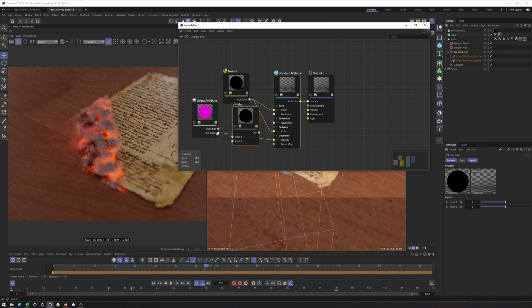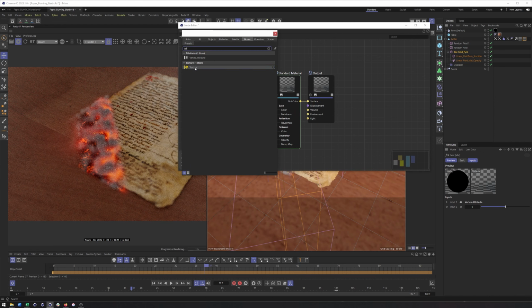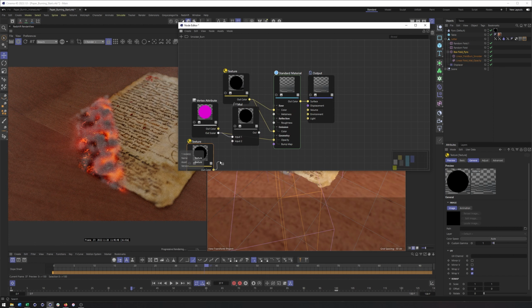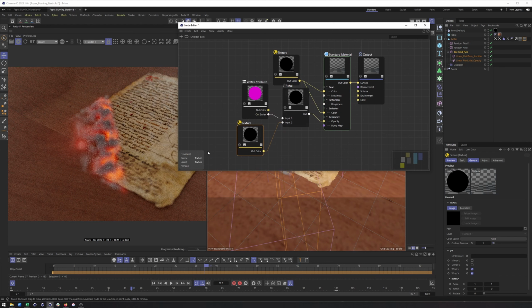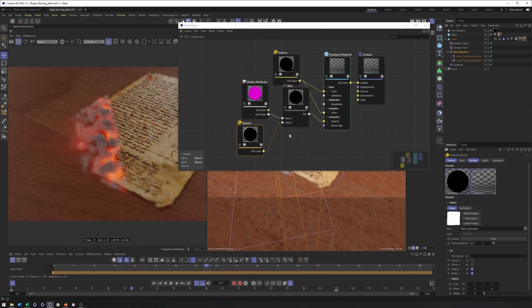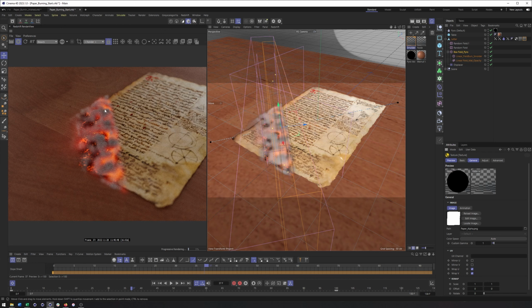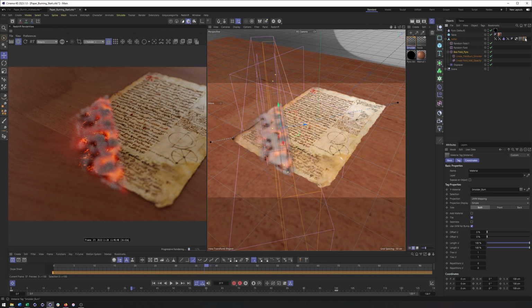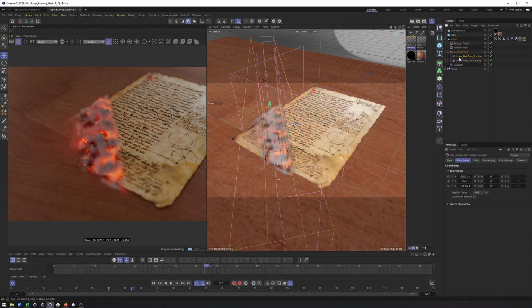and our texture, the alpha texture for the paper, just to make sure we don't get the material visible on those parts, since those parts are in fact hidden. So there it is. Okay, so that should look a bit better. And while I think we're probably seeing a bit too much of this, I would almost prefer that over the opposite. And we've just stacked the material using Cinema 4D's new kind of Redshift's ability to take advantage of Cinema 4D stacking. I can always come in here, find that, oh, that wasn't a linear field. This was a box field.